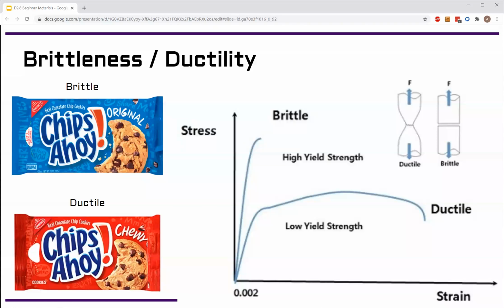Ductile materials are also normally able to change their shape, so you're able to bend them intentionally and they'll stay together, able to form them into different shapes. So sometimes that can be a big advantage. Sometimes you want a brittle material that has this higher yield strength, this higher breaking strength, because that's what you're looking for, and that's how you need the part to behave.